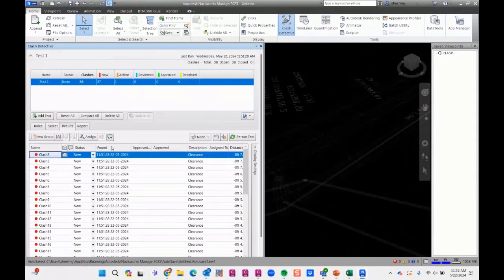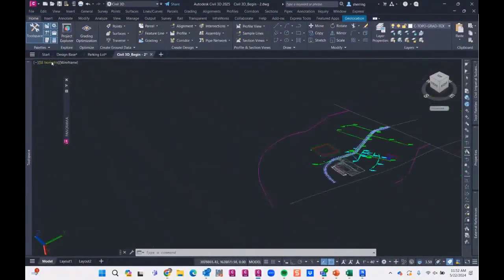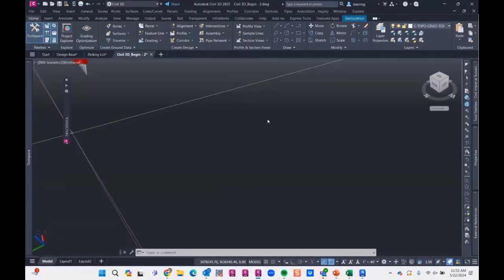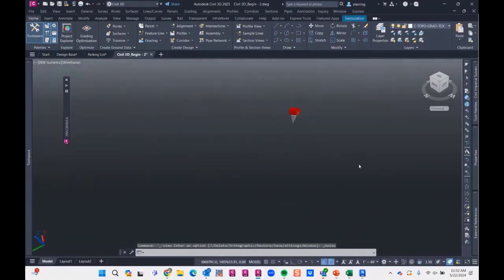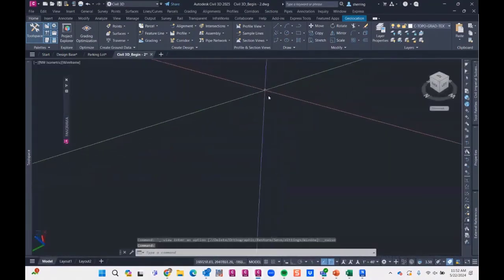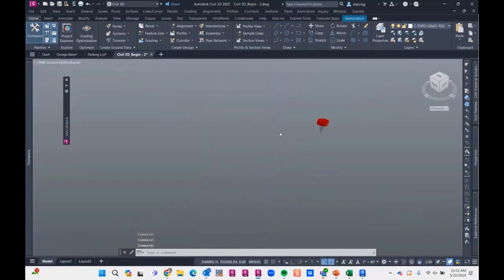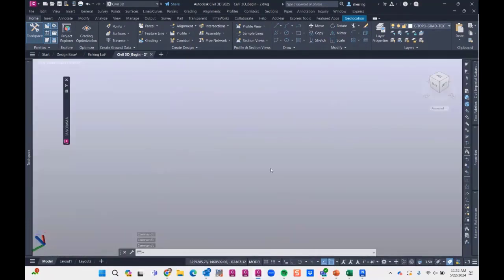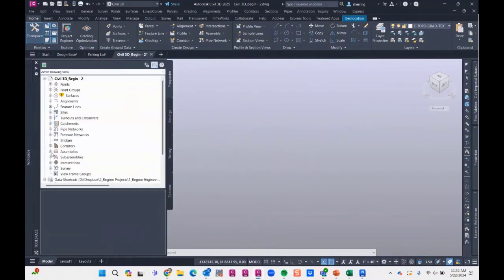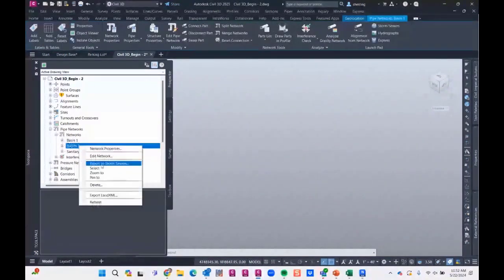Okay. Question. Is there a way you can go into that 3D viewer in Civil 3D without the Navisworks? Yeah, any view, you can go into an isometric view, but then you're stuck with mixing 2D and 3D and wherever that pipe was. Yeah, you can rotate your viewport. You can do anything you want. It's just not as pleasant. The way I do it, if I don't run a clash, I go to my networks and I just select them here.